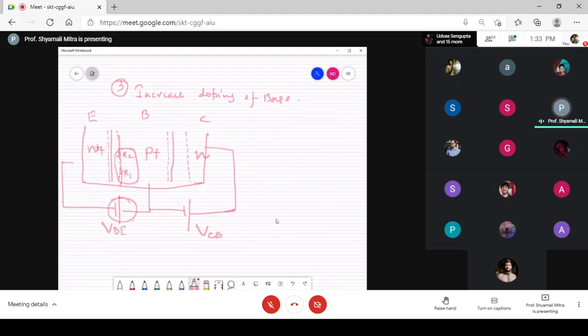If we can make a transistor now with a base not very thin, not also very wide, what another aspect now do we encounter? With the increase in VB, the potential barrier is lowered. With the increase in VB, the potential barrier here on this side will be lowered. Thus, a whole bunch of new electrons can pass onto the P region. Also, a whole bunch of new holes can pass into the N region on this side. But note that this is not a good thing because now holes after going to this N side are lost due to recombination. And this is the emitter injection efficiency loss.